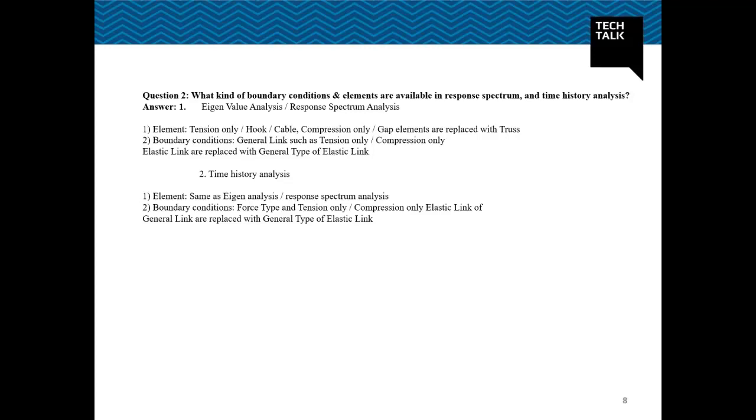Let's say I have provided tension only springs and I am performing moving load analysis. One frequent question that I receive is that tension only springs are converted into linear springs in moving load analysis. Why is that? There is one beautiful knowledge base article on this, which explains why considering tension only springs or compression only springs as linear springs in moving load analysis helps in reducing the effect in the overall load combination.